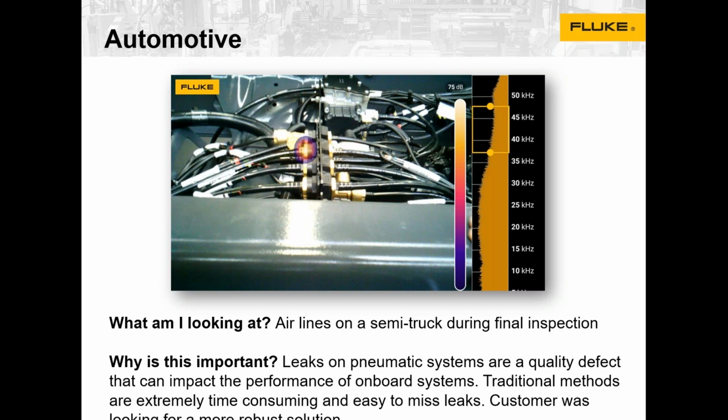They've got large amounts of compressed air to operate some of the different things on the truck, and as part of their production process or quality control on their production process, they would have a group of folks go around with an ultrasonic leak detector and inspect each of the different connection points for these pneumatic lines. And so it was just part of their quality assurance in their production line. And we went in with an II-900, and we were anticipating looking at exactly what the tool was intended for when we launched it. So we were going to go and try and find areas to improve their energy savings capabilities.